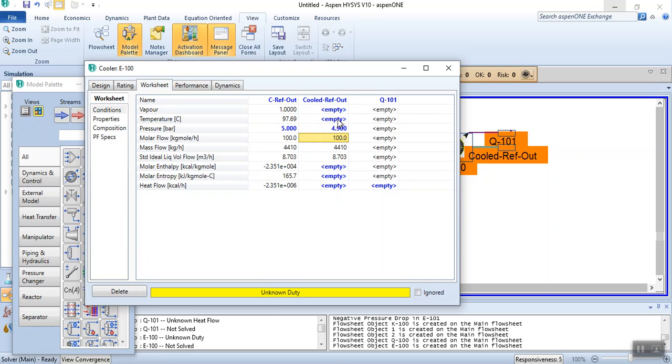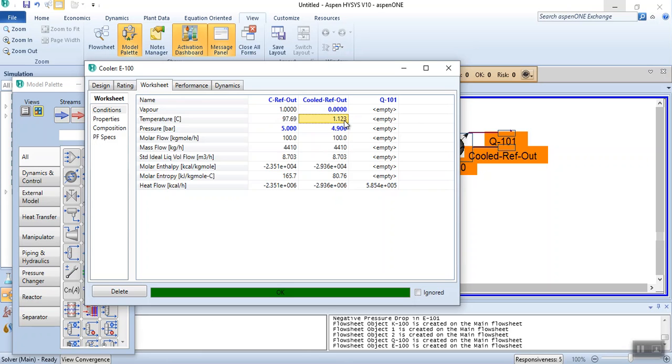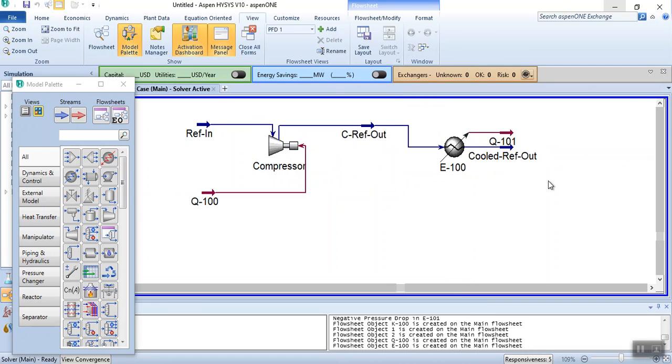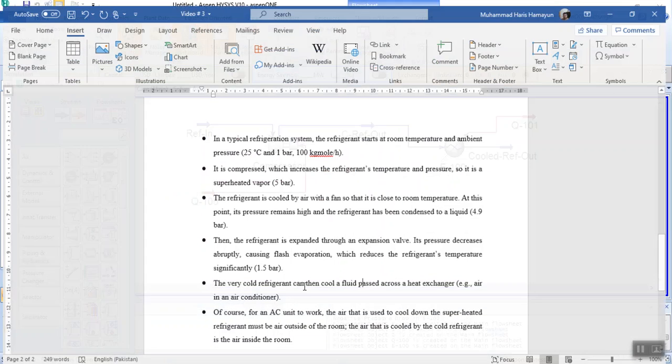It means you are left with this value, which is the vapor, and you have been given the condition that it has been condensed to a liquid state. I have earlier told you in this video a few moments ago that if it's 1 it's in vapor state, if it's 0 it's in liquid state. So simply enter 0 over here and you can see you have got the answer. So again you have entered two parameters, vapor and pressure over here. Okay, that's very simple.